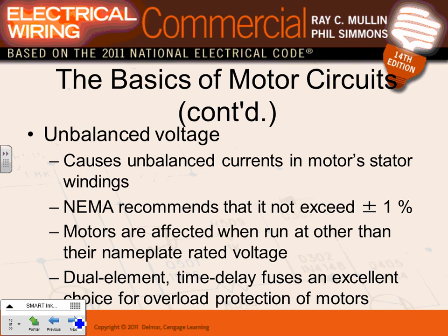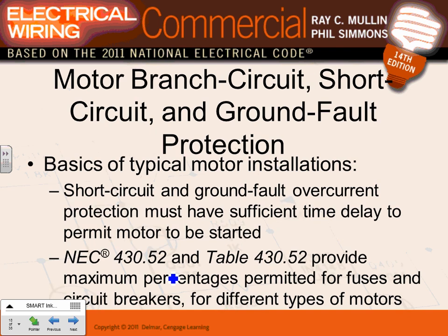Unbalancing the voltage can also cause your equipment to burn. So if you have a NEMA, I think NEMA goes for 5 to 10% plus or minus voltage drop. So if you have an unbalance in the voltage, guys, it will also affect your motors. So motors will burn. Why? Because it will create an unbalance in the current. I have a table, and it will affect the operation of your motors.